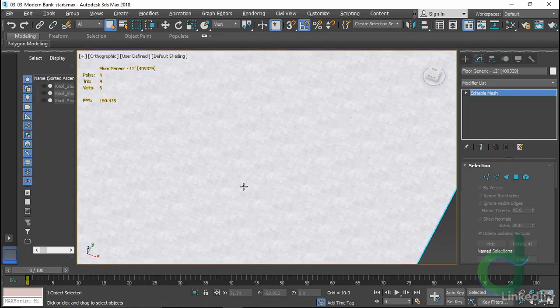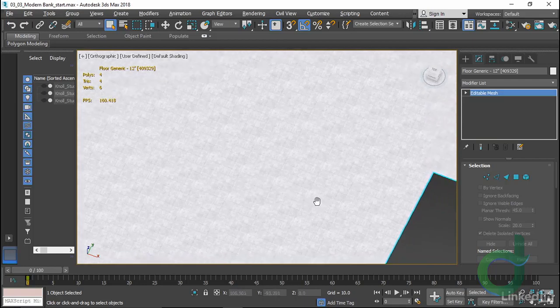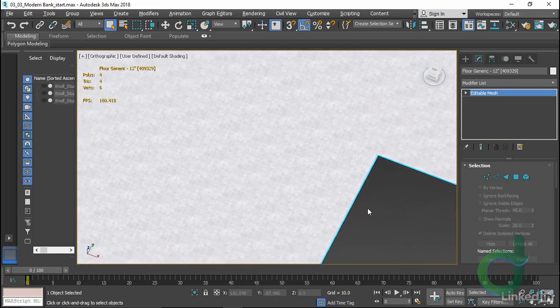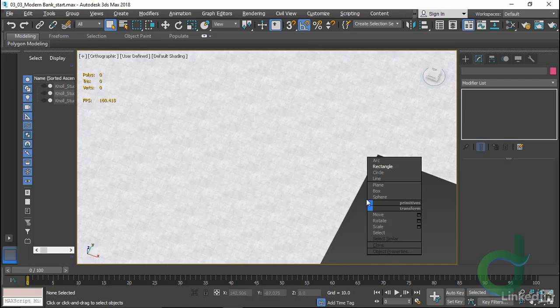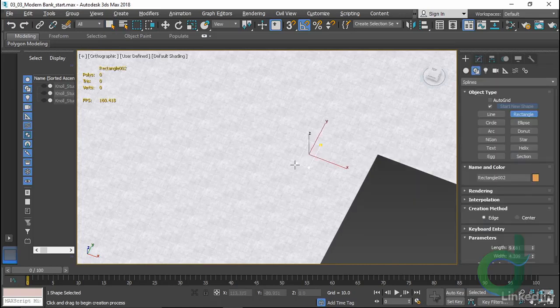We can see the default mapping from Revit is maybe a little bit small. As a gauge, I'll lay over a rectangle, holding Control to make a square. And we can see in here, when I make a rectangle that's roughly 4 feet on a side, we can see how many tiles we get. So we definitely need to map this properly.